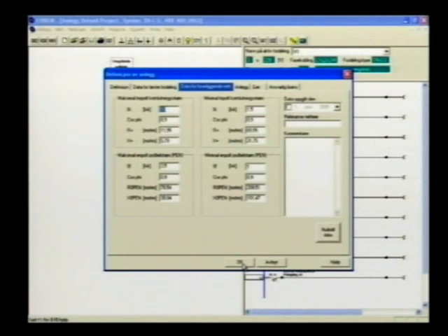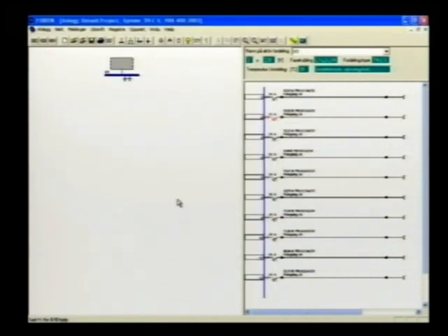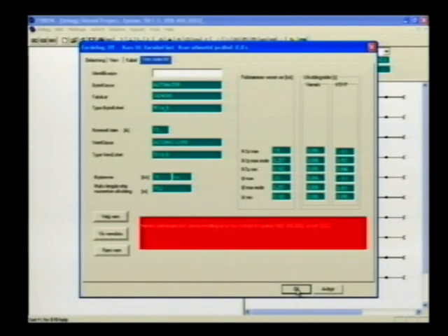But we need to do some calculations, and then we need to know the short circuit currents at the origin of the installation, and that is not available in the IFC model. So I have to provide that information, and then I just click there, and we have some default values which I just accept, and then okay, and then FEBDOC verifies all circuits if they are in compliance with the regulations, and of course there is still a red device, so I have to look there and see what's wrong.